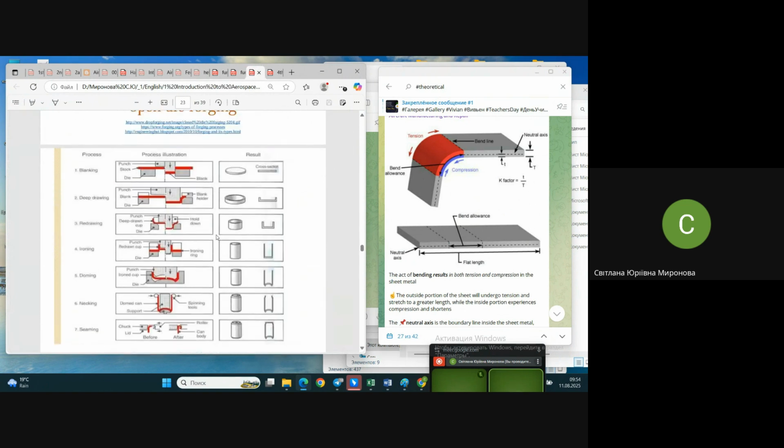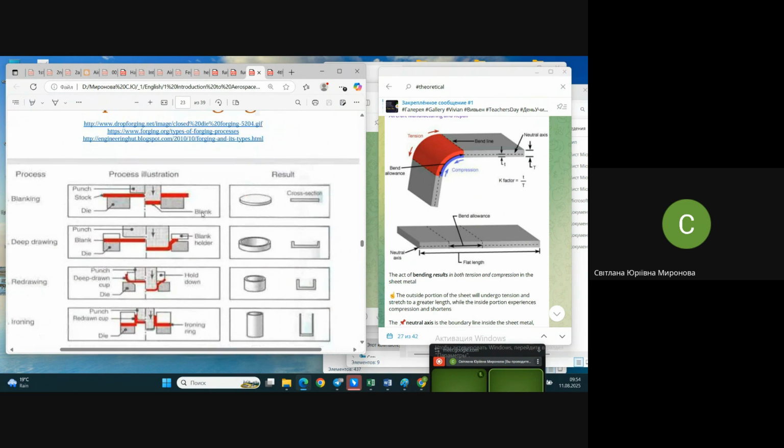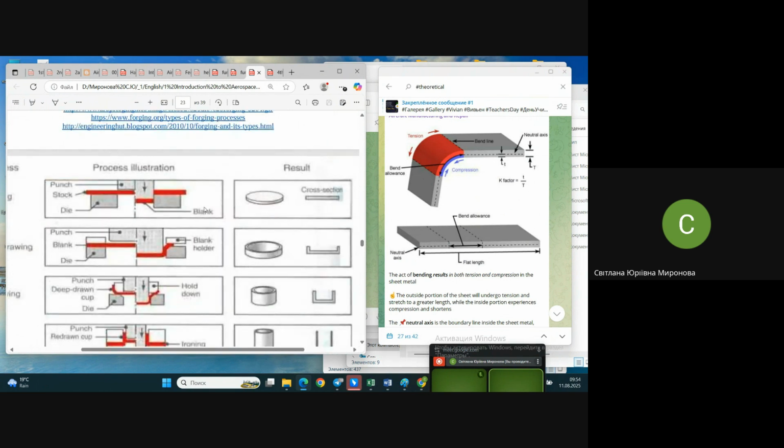And we have seen in a picture practically the same scheme: die block, punch, piece of sheet metal, but it's maybe finished either with a deformed part, with some deformation like a cap-like part, or it's maybe finished with cutting of the shape.